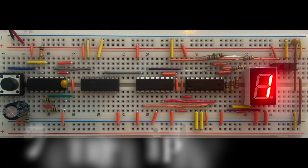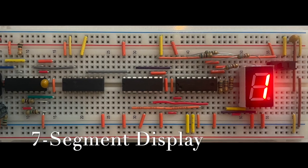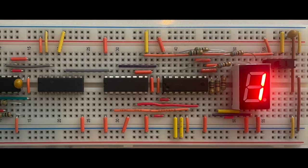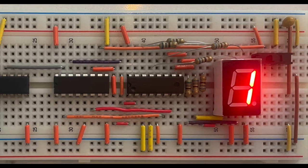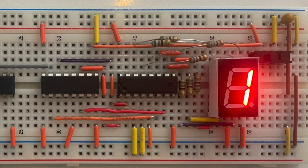The output from the 4511 is sent to the 7-segment display. This display shows one digit at a time using 7 individual LEDs arranged in the shape of a number. The common cathode version is used, where all cathodes are tied to ground. Each LED needs its own resistor to prevent each number from being a different brightness.